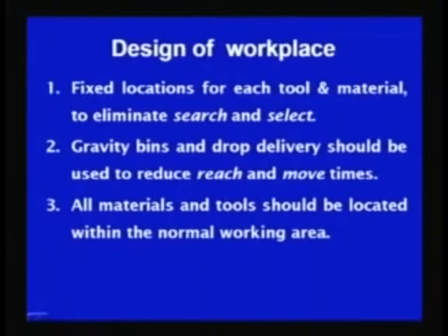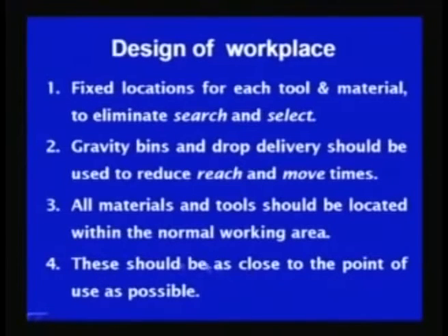That is why the material and the tools are to be located and placed in such a way that the operator can use them easily with the coverage of the minimum distance, and that is why these should be located within the normal working area, so that the worker will not be required to put unnecessary extra effort for carrying out the job. This should be as close to the point of use as possible.